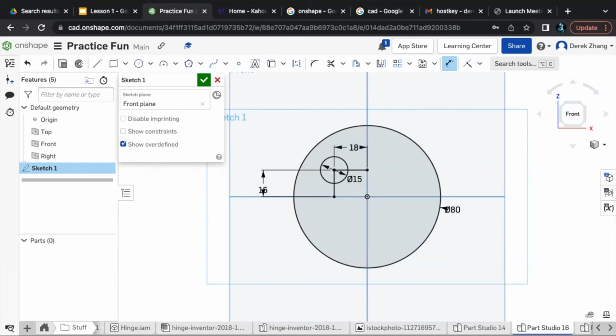Now we're going to draw the second, actually, I think that you guys are advanced enough to know the mirror tool. Drawing that circle with those lines is a lot of work. What if you don't want to do that? After you've drawn it once, you see this little icon, like 2 L's at the top, that says mirror. Click on that. First, the top says select the mirror lines, so select this line that goes through the middle of your emoji. Does everyone see that?